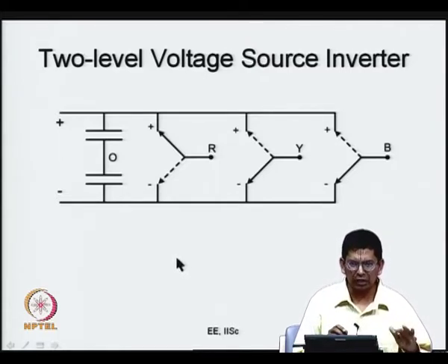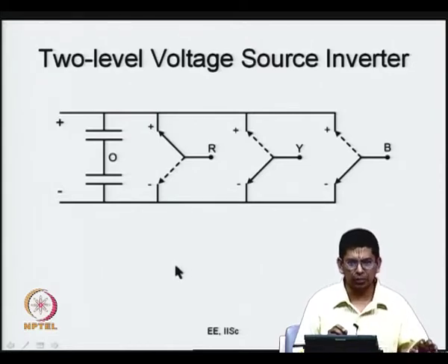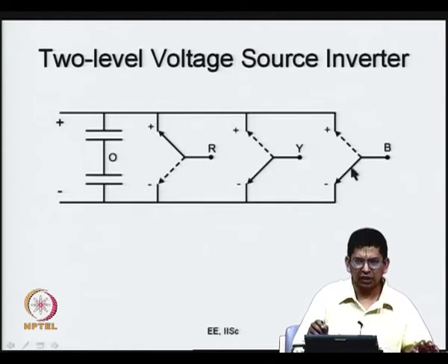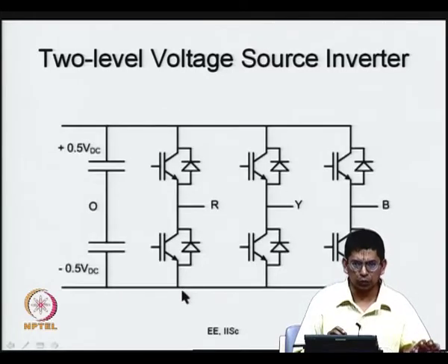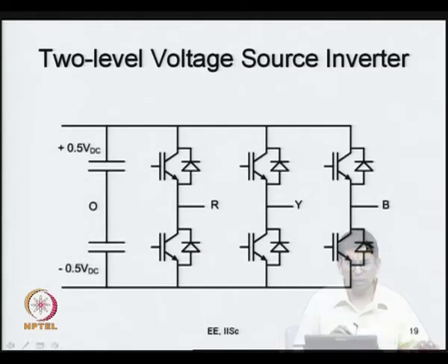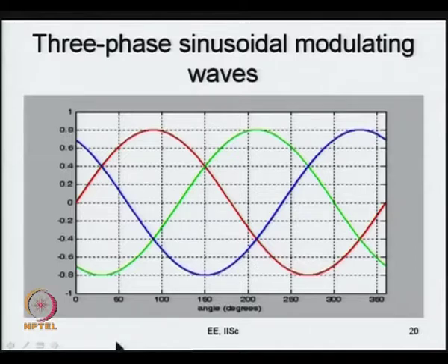So, we just prepared ourselves by going through single phase inverter which has only 2 legs before we tackle the problem of 3 legs now. So, you have 3 legs and all the 3 are single pole double throw switches, and they are realized in terms of switches which switch in a complementary fashion as we know. So, what we do now, in the case of unipolar PWM for single phase inverter, you simply use 2 sine waves which are phase shifted by 180 degrees.